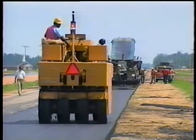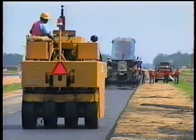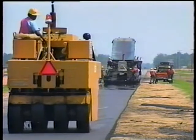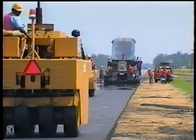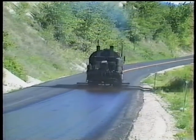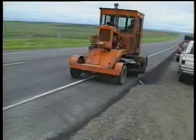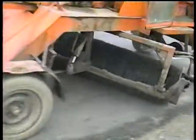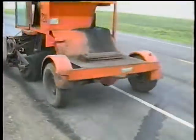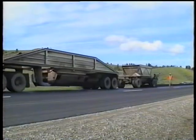First, get familiar with the equipment that will be used. The paving train consists of haul trucks, a paver, and 2 or more rollers. A distributor applies the tack coat to bond the pavement to the underlying surface. A power broom sweeps off the surface ahead of the tack application. Now let's take a closer look at each, beginning with haul trucks.